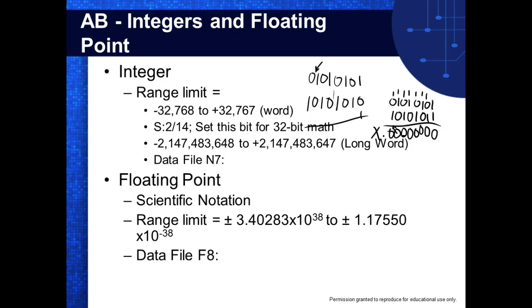So I don't think the 1100 supports this, but on some of the Allen Bradley PLCs, you set the status register, or status data, to bit 14. It allows you to do what? 32-bit math. And this extends our range up to a minus 2,147,483,648 to 2,147,483,647. But we still have what? One negative more than we have positive. And why is that? 0 doesn't have a sign. So there's no such thing as a plus 0 or a minus 0, right?